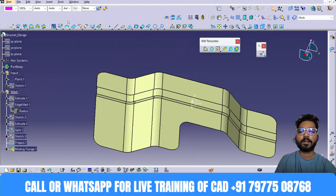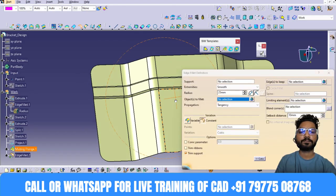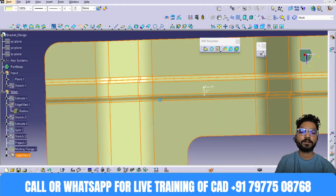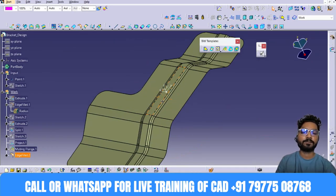And now we'll apply fillets for more smoothing. So fillets: select this edge, select this edge, select this edge, and select this edge. A 5 mm fillet will apply. So a properly smooth mating flange is created here.